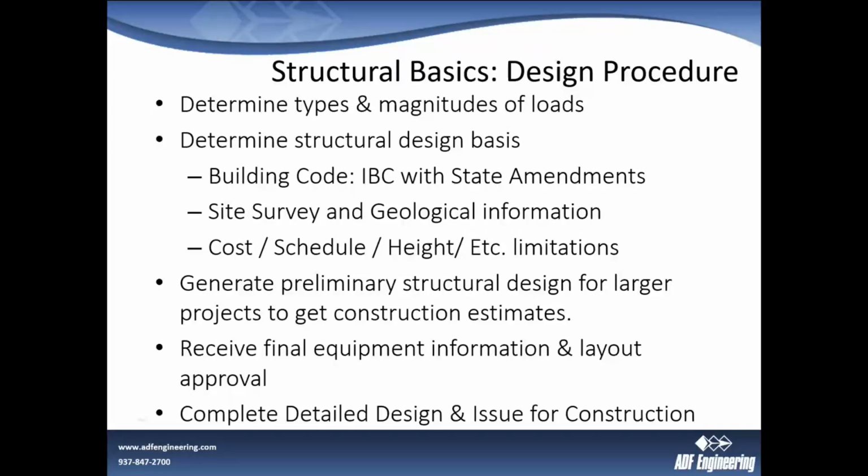So when we start a project, the first thing we really need to do is determine what kind of load we're going to be dealing with and how much. A lot of the projects we do, and a lot of the stuff we see on sites, is related to a process upgrade. So we will have a lot of ideas of what the equipment needs to be, what the changes need to be done there, and we will have to look at it in terms of what does all this weigh? How much space is this going to take up? And that kind of sets our structural basis for design.